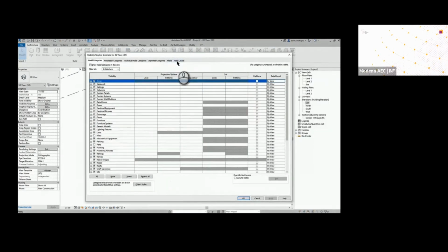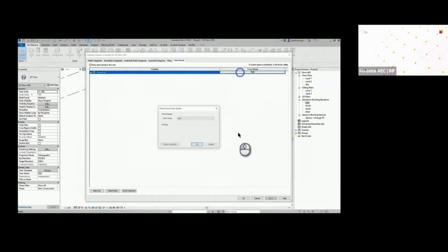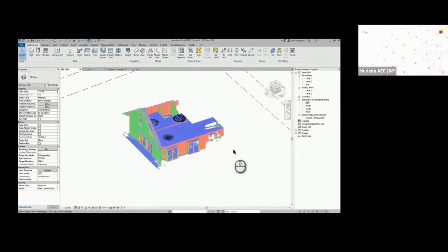So by utilizing Revit's visual graphics box, you too can go to your point clouds, select for the coloration, and of course change. In this demo, I'm utilizing the normals field. The idea behind this is the moment I select a normal coloration, Revit starts applying 3 different coloration types to 3 different faces of my model. Green for left, red for right, and blue for top. I get a better in-depth analysis just looking at the model now because I can identify key views within my model.